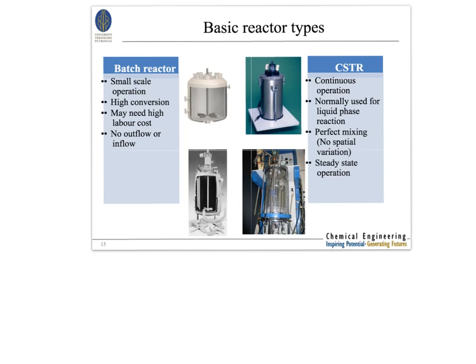Okay, by now I hope you have a clear understanding of what a reaction rate is. Now we look at the 4 basic reactor types. We have batch, CSTR, PFR, and PBR. The selection of reactor depends on the reactant phase. Normally for industrial application, for liquid phase processes, we use semi-batch or CSTR, while for gas phase processes, we use tubular reactors.